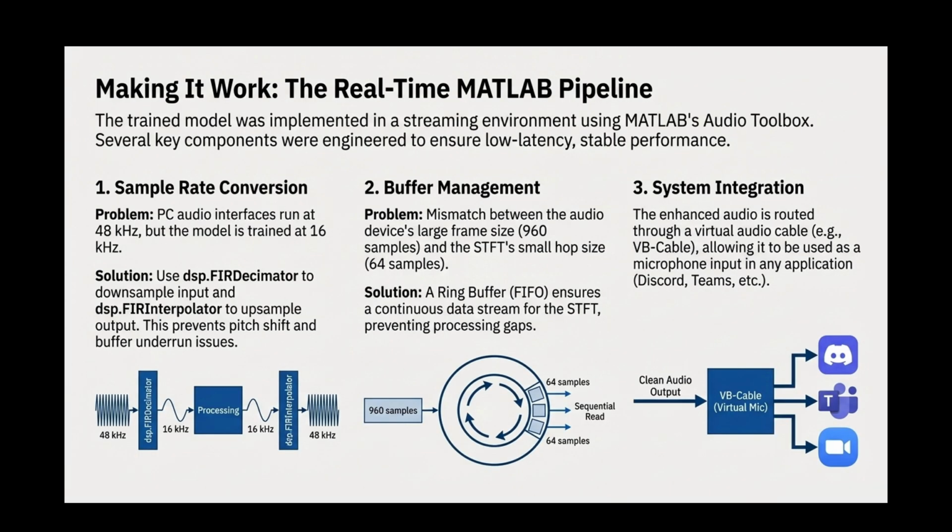Making the model work in real time required engineering beyond the network. First, there's a sample rate mismatch. Many audio devices use 48 kHz, while our model runs at 16 kHz. We handle this with downsampling before processing and upsampling after reconstruction.